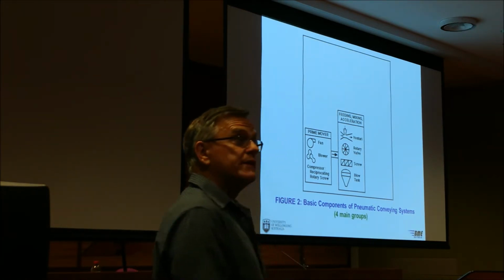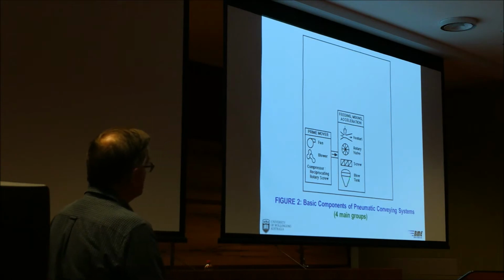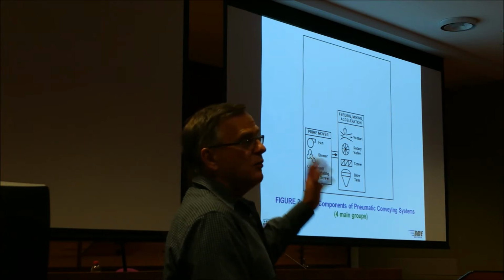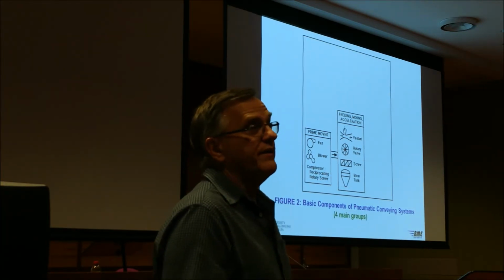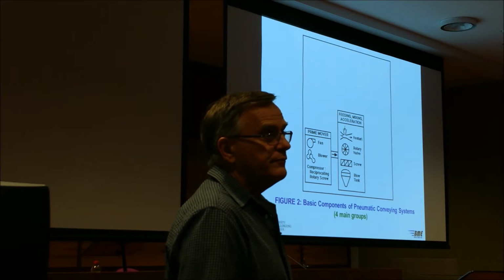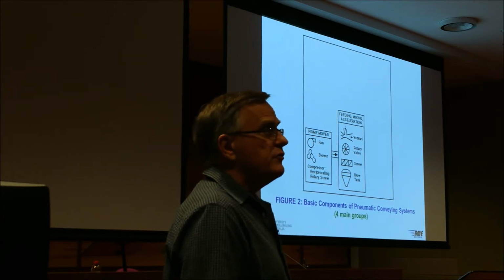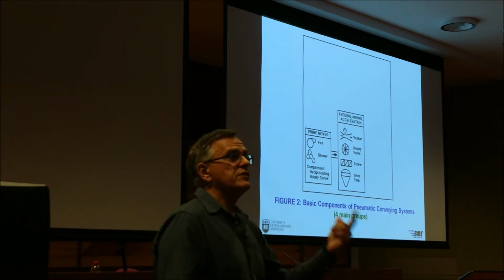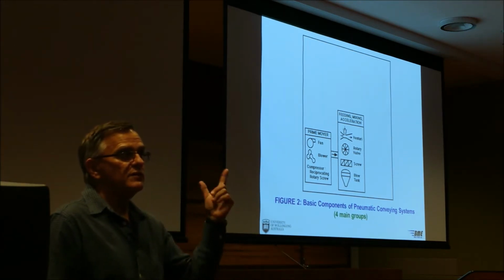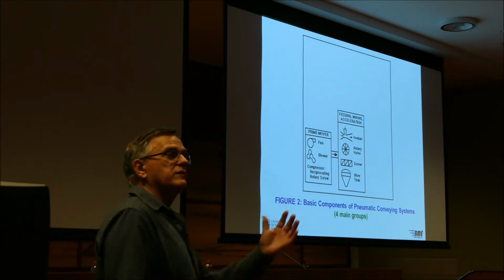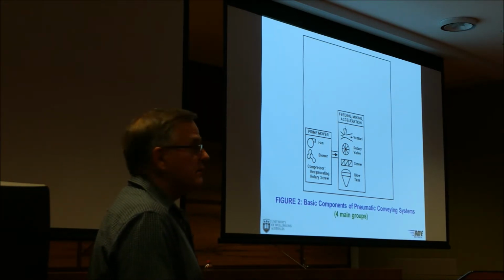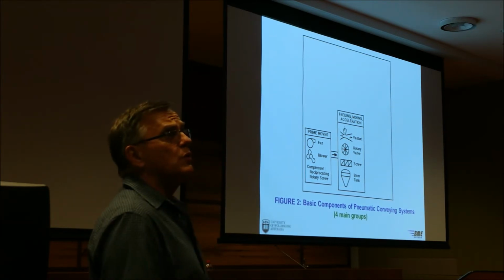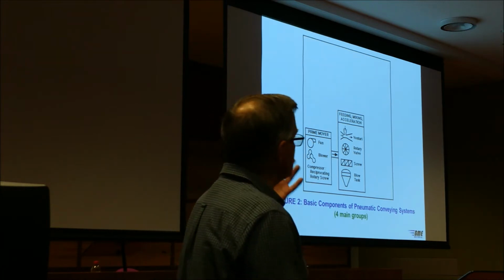And if you need more pressure than that, you can go to the pressure vessel, or blow tank, we call it. That's a certified pressure vessel, and that can operate up to 500, 600, whatever you want, 1,000, 2,000 kilopascals gauge. When I talk about pressure units, I talk about gauge generally. There's also gauge units, and there's also absolute units. Okay, so we have to be specific about that, and that's why I always like to emphasise that as I talk about those sort of numbers. Alright, so depending on your pressure requirements, also your product properties, you will select a suitable feeder.